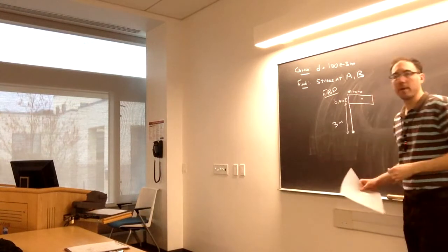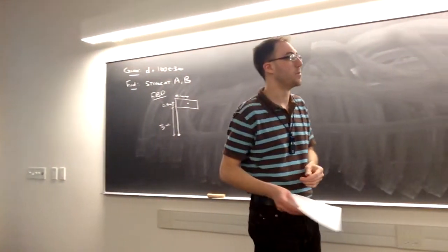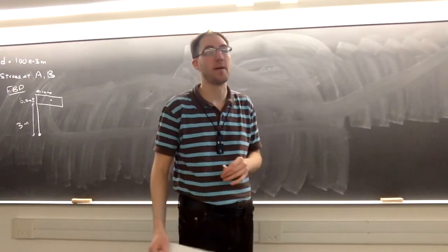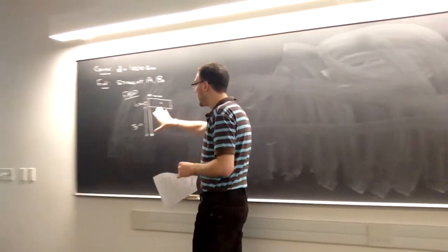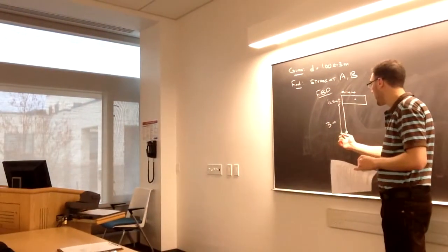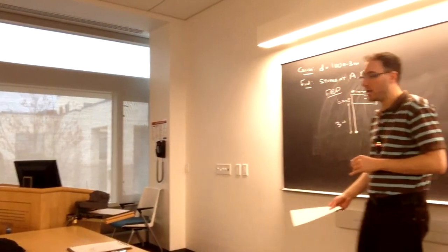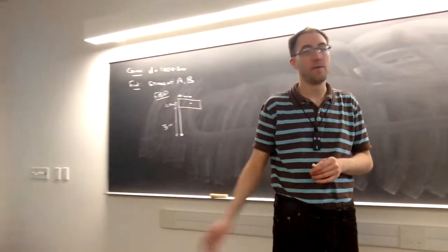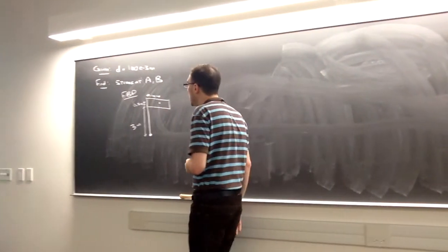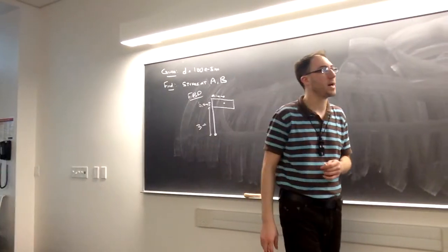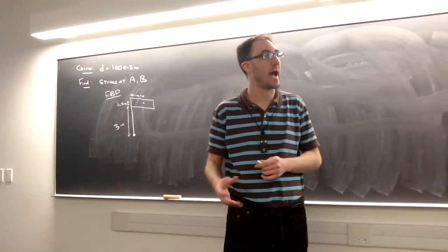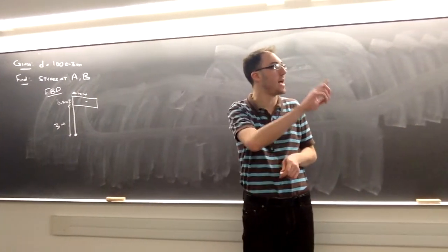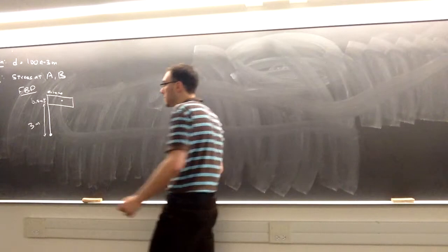So in this diagram, we can simplify this distributed wind load that's uniform. They give us the pressure of the wind, 1.5 kilopascals. In this picture, since we're going to be looking at what the internal loads are at that cut, we can simplify the distributed load down to a point load for this analysis without changing it. So that wind pressure, I can simplify to a point load acting at the centroid, since it's a uniform load, acting at the center of the rectangle.